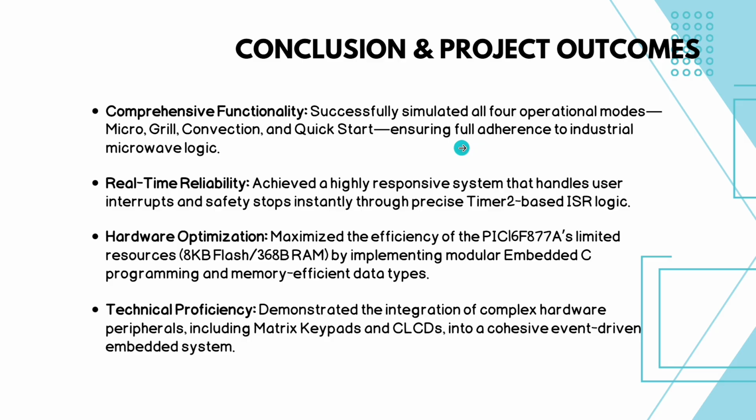The last, conclusion and our project outcomes. The comprehensive functionality successfully simulated all 4 operational modes, like micro, grill, convection, and quick start, ensuring full adherence to industrial microwave logic. The real-time reliability achieved a highly responsive system that handles user interrupts and safety stops instantly through precise Timer 2 based ISR logic.